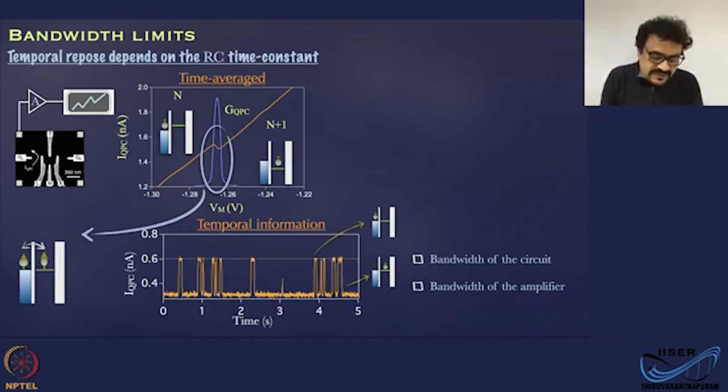So generally what you have is a quantum dot device, and when you are measuring the current through the sensor, that is the channel, you will get a bump-like structure, or peaks in the conductance, as a function of one of the gate voltages, and that is going to tell you when the charge transfer is going to happen.